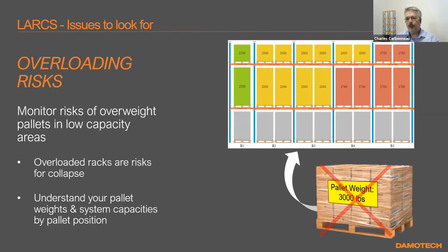And then in B4 and B5, I've got these variations, right? And sometimes when we see that it's non-uniform, we can help you and say, well, it's non-uniform because the first beam elevation on bay 4 is smaller than the other ones. And it's the same for bay 5. So if you change your beams back to what it should be, then you will have that 2,000 pound uniform for these bays.